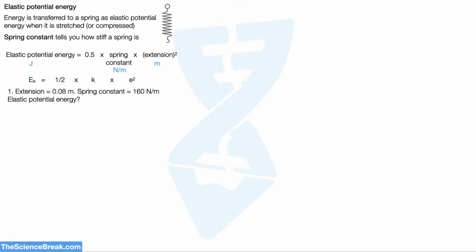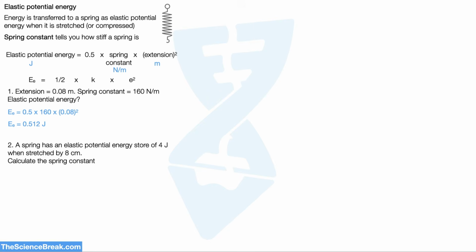The extension of a spring is 0.08 meters. The spring constant is 160 newtons per meter. What's the elastic potential energy? We substitute into the equation, very straightforward. Don't forget to square the extension. And we end up with an answer of 0.512 joules. Next, we have a slightly trickier question.